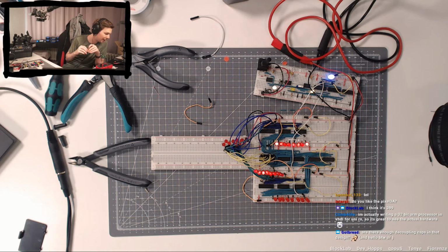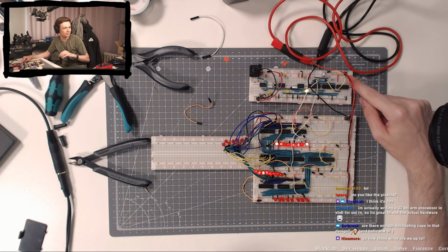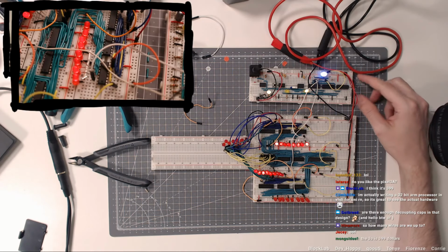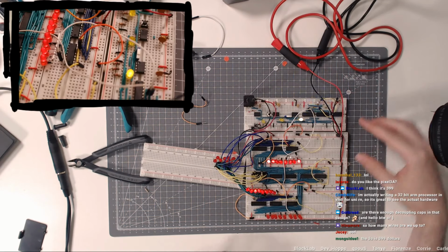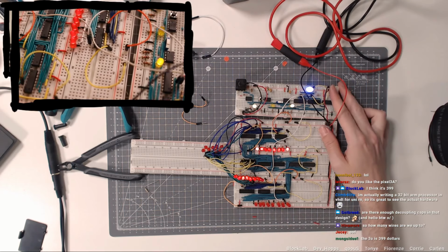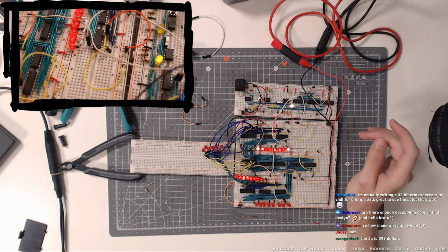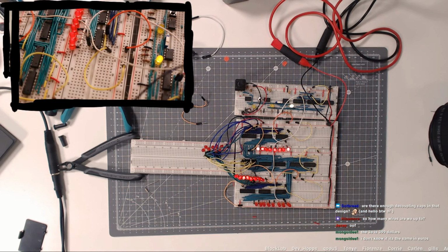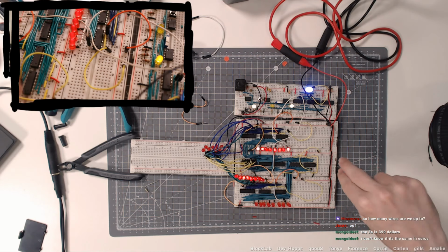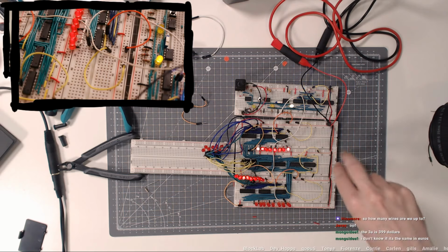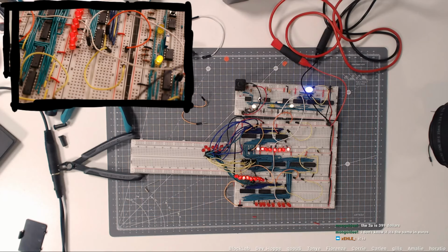Are there enough decoupling caps? We have only one up here right now in the corner. That's all so far. But so far we haven't seen any issues. Once we add more modules and we build the bus and everything, I definitely want to improve the power supply. I want to put proper wires around the border and solder pins on that main wire so that each component gets the proper power from the power supply.